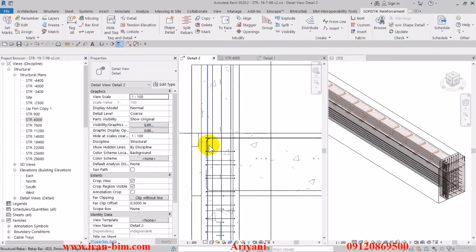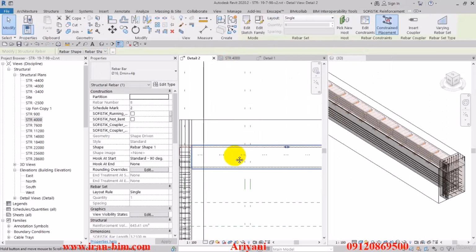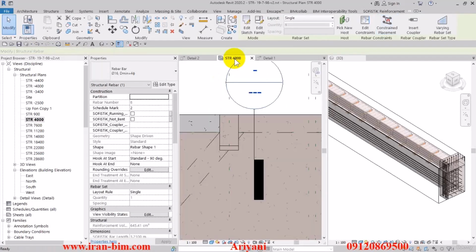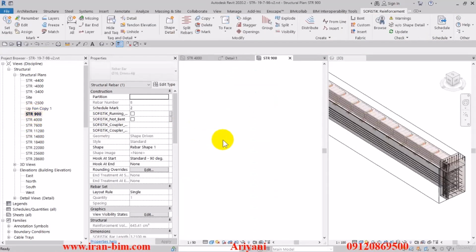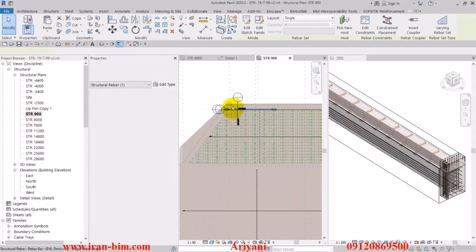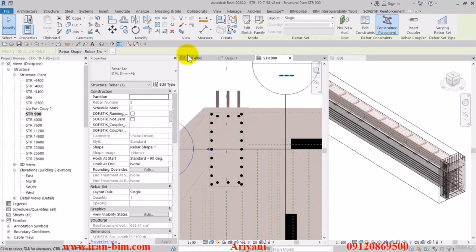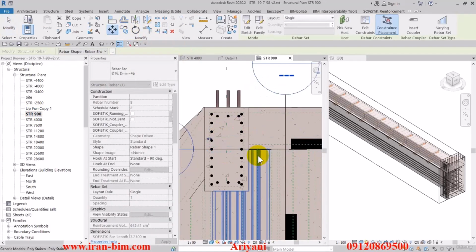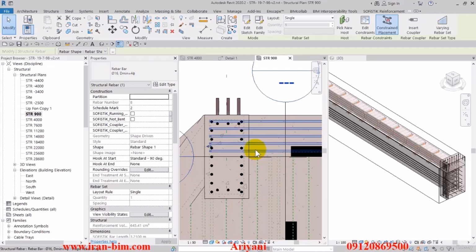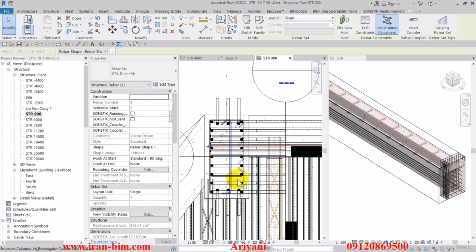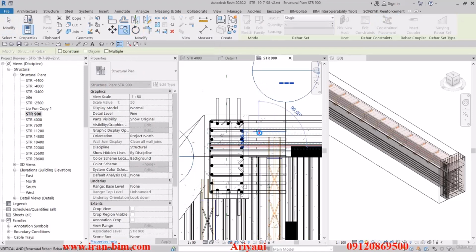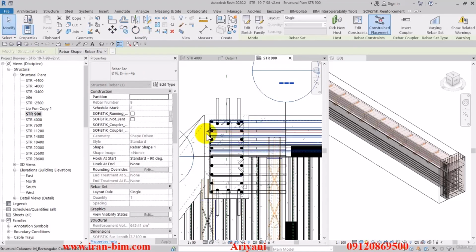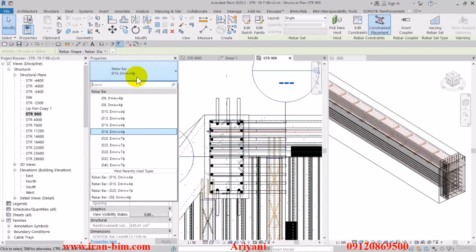All right, so now I'll go to the top view. Here, open up the structural level of the height of 90. It's right here. So select this and using the move tool, put it over here. All right, right click and select wireframe now. And now I'll copy this and paste it over here. And then I'll put this one on type 22 instead.